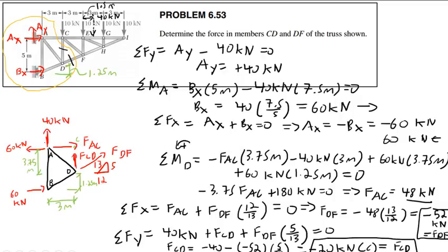The method of sections. So again, the power of the method of sections is that it allows us to directly leap beyond where we would otherwise be. If I wanted to do this using the method of joints, I have no zero force members here. So if I want this one, I'm going to first have to draw a free body diagram of this joint. I could draw this one, but that's not going to help me at all because I have way too many unknowns. So then I could draw a free body diagram of this one to get this one and this one. That's still going to have a lot of problems because if I draw this one, oh my god, I'm probably going to have to start from this end, get this one and this one, then maybe do this one, this one, this one, this one, this one, and this one.